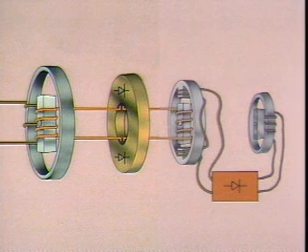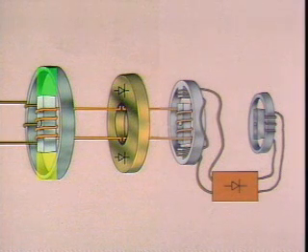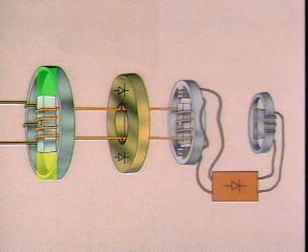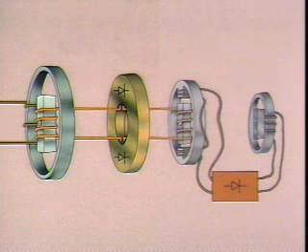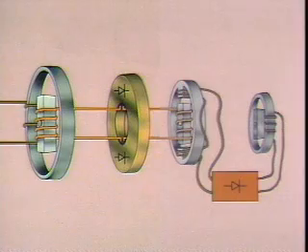This direct current creates a magnetic field around the generator rotor, which is used to induce voltage in the stator windings. So, in a brushless exciter, the entire process of creating magnetic fields and inducing voltages from the permanent magnet generator to the main generator is performed without the use of brushes or slip rings.